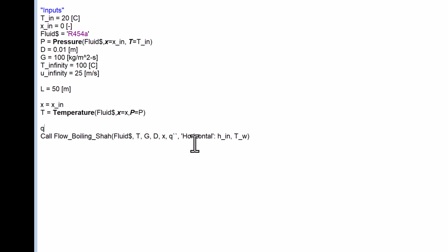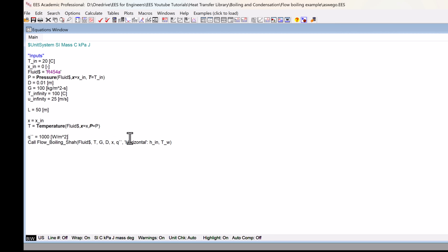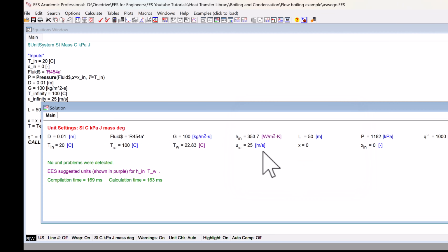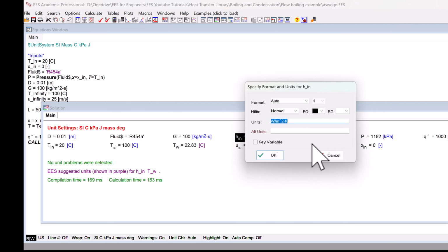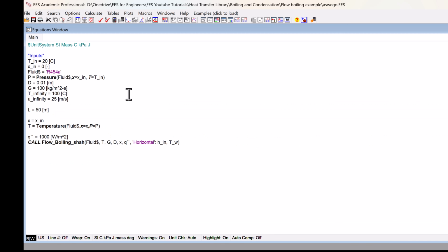So what I'm going to do is set a heat flux to something, I don't know, reasonable. It's probably a little low. And I'll have to come back and adjust this heat flux so that it's consistent with the air temperature and the resistances that separate the air temperature and the fluid temperature. But right now, I can use this heat flux and I can solve. And for this heat flux, I find out that here's the heat transfer coefficient and here's the wall temperature. Okay.